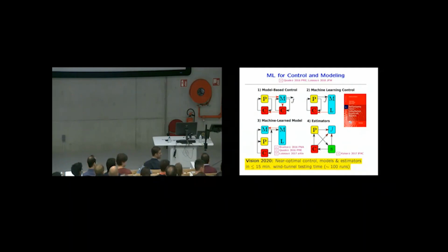Yes? Did you try the von Karman wake with the machine learning control? The answer is I would have liked. We did it for a slightly different configuration, a fluidic pinball. So 3 cylinders rotating. But I'm pretty sure I know what would be the outcome. The outcome will be phasor control. If you look at the dynamical system describing the von Karman vortex shedding, then the machine learning control gives you phasor control. I think we would get the same thing also in the original plant. I would have liked to do it, but our resources are limited. Good question. Thanks.